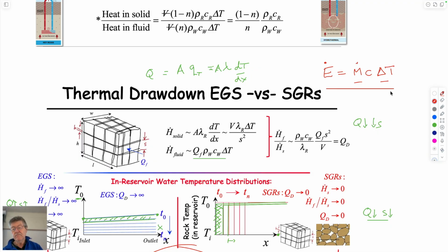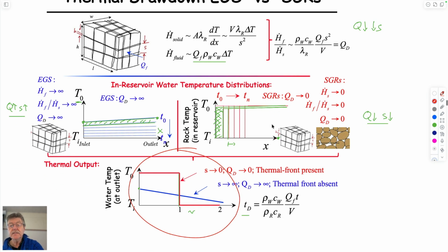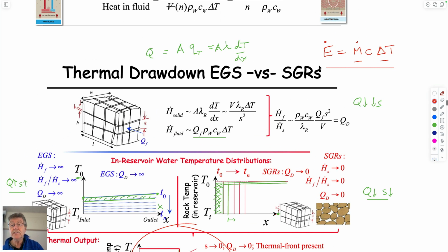What we talked about at the beginning of today and on Tuesday was making sure that flow rate is maintained through the system. That's not the only parameter we need to take care of. We've got to make sure that it goes in cold and comes out hot, that there's some heat transfer in the system. And understanding that behavior, understanding this equation, actually is the baseline of us understanding how geothermal systems work.